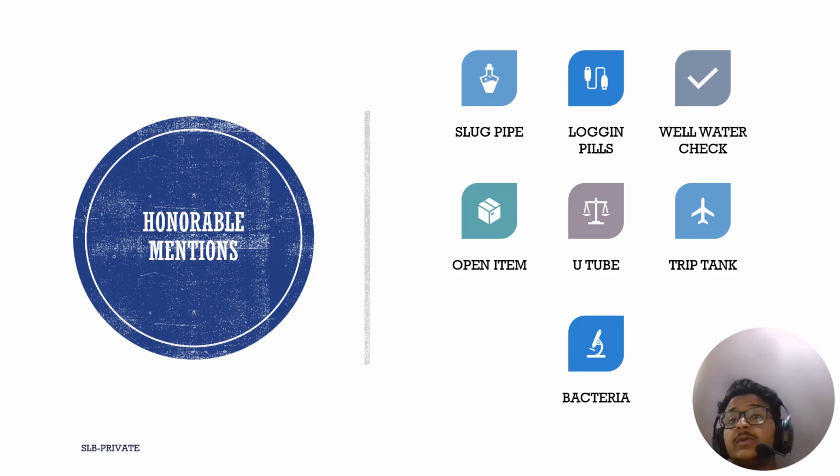Also, we have the U-tube. U-tube is when having multiple mud weights in the same wellbore. It can cause you a lot of trouble. Multiple mud weights with the same fluid can push each other and make it unstable down there.